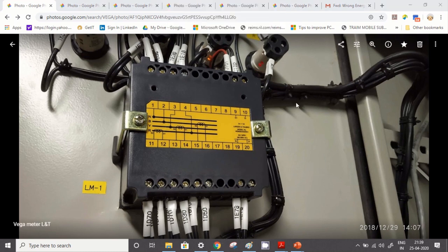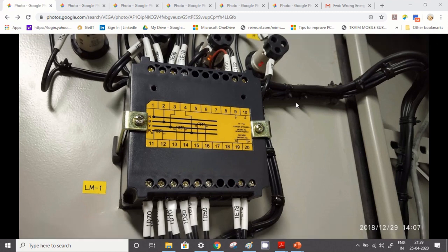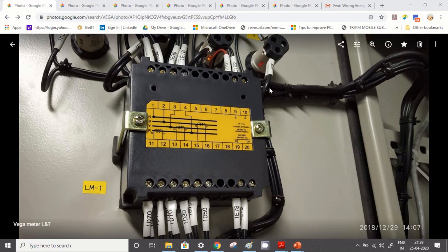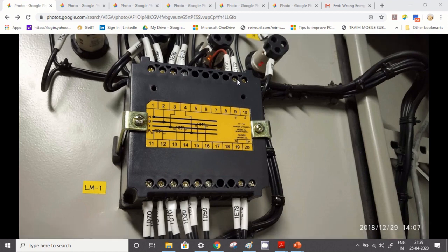Even after doing all this, if your data is still not showing in the SMPS, and the AC communication fail alarm is also present in the SMPS, then you can try one more thing. Bring one small cable, remove these two cables, connect your new cable directly here, run it on the surface, and take it straight to the SMPS. Connect this cable to terminals 31 and 32, or 33 and 34, or 35 and 36 in the Vertiv or Emerson make SMPS. So if there is any chance of breakage or a continuity problem in this RS485 cable, that doubt will also be cleared.